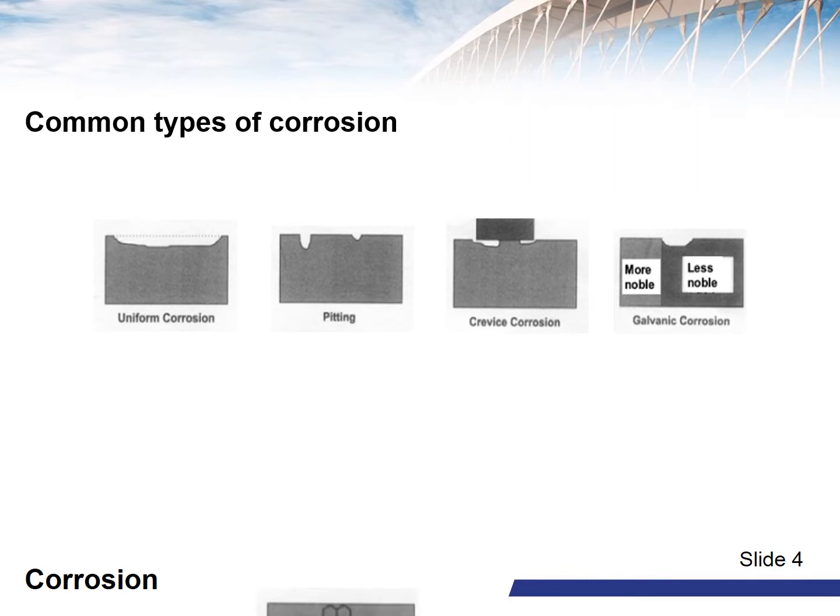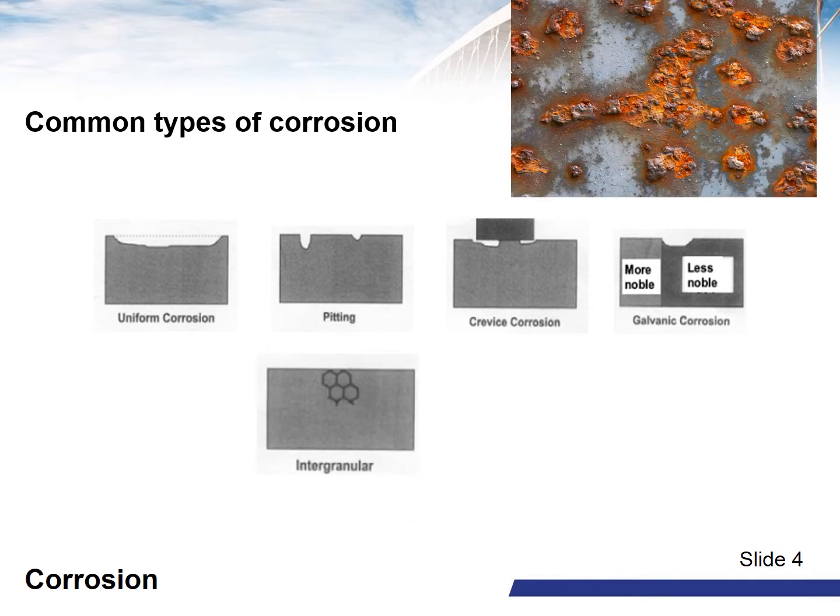Intergranular corrosion. This corrosion occurs when impurities are present at the grain boundaries which form during solidification of an alloy. It can be caused by the enrichment or depletion of an alloying element at the grain boundaries. This type of corrosion occurs along or adjacent to the grains, affecting the mechanical properties of the metal despite the bulk of the material being unaffected. However, this is generally only an issue in structural applications where welded components are used.